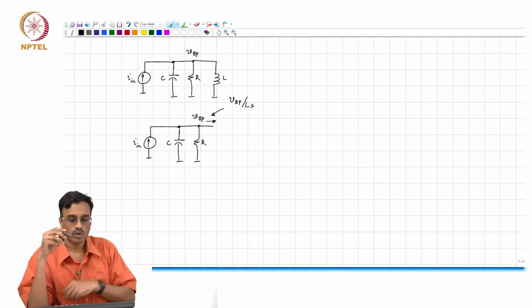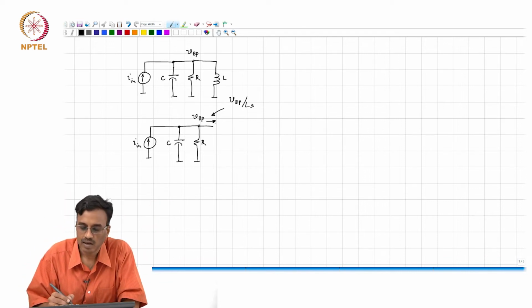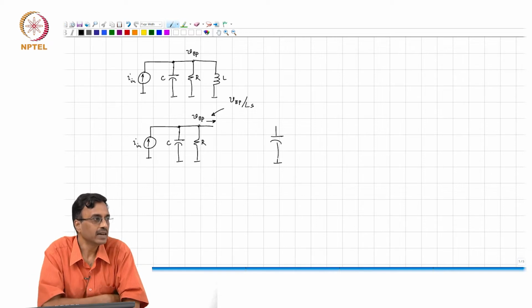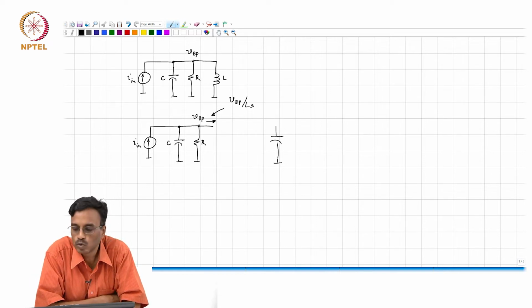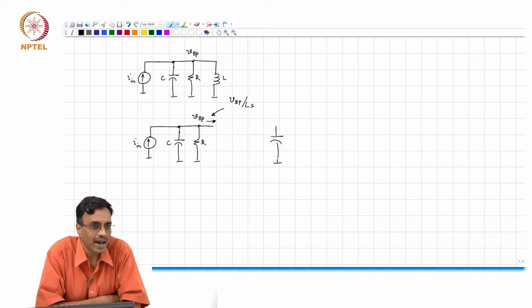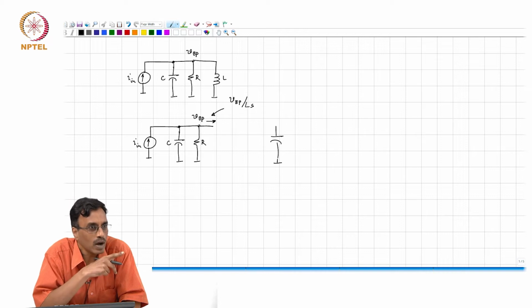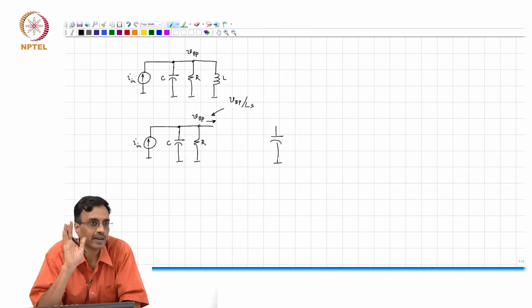Our capacitor can only integrate current, but we need to integrate voltage. We can convert the voltage we have into a current so that the capacitor can integrate it, and the capacitor will generate a voltage, but we need a current, so you can convert the capacitor voltage back into a current. That is the basic idea.